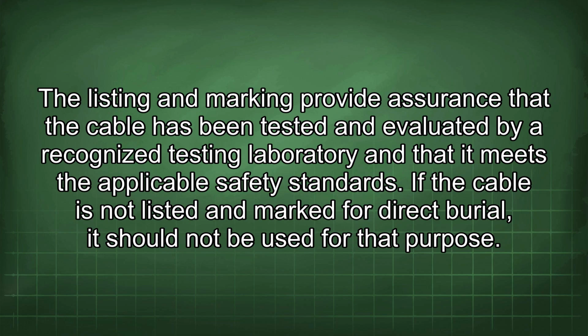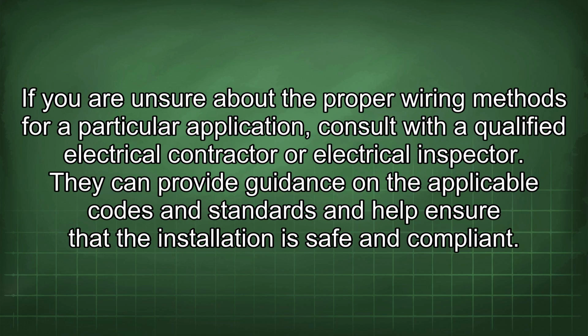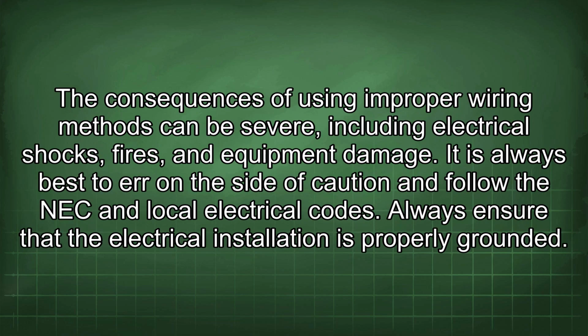If the cable is not listed and marked for direct burial, it should not be used for that purpose. If you are unsure about the proper wiring methods for a particular application, consult with a qualified electrical contractor or electrical inspector. They can provide guidance on the applicable codes and standards and help ensure that the installation is safe and compliant. The consequences of using improper wiring methods can be severe, including electrical shocks, fires, and equipment damage. It is always best to err on the side of caution and follow the NEC and local electrical codes.